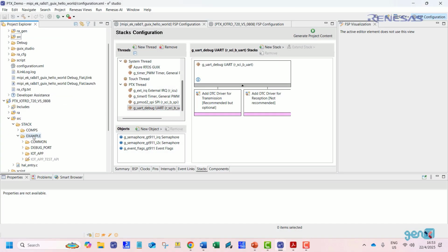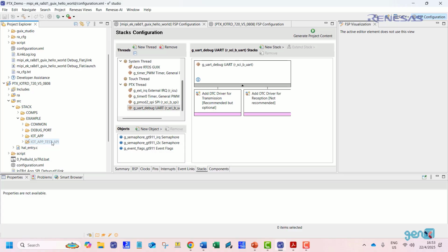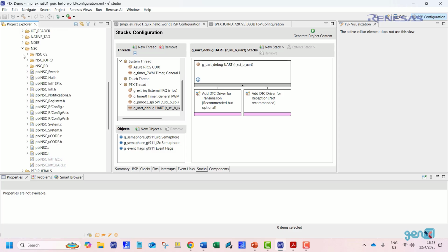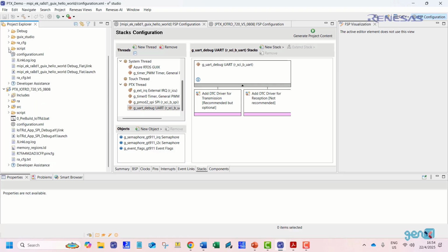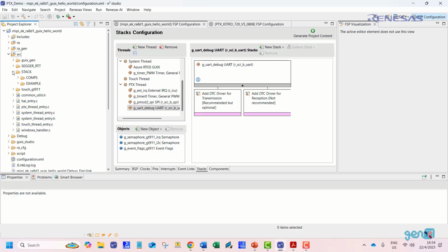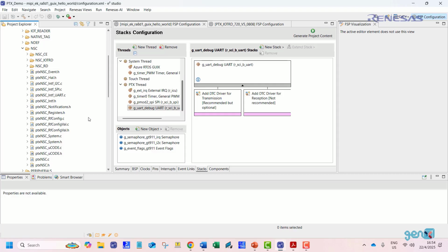Now that the files are added, we need to remember that in our previous project, we likely had a custom build configuration that excluded some files we didn't need for this operation. By pasting these files into our existing project, all of them are now active and part of the build. To resolve this, we will go through the files individually and exclude the files we don't need for this demo.